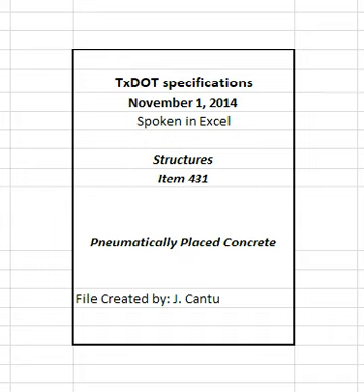Place coats on vertical and overhead surfaces in layers of such thickness to prevent sloughing, sagging, tearing, or debonding. Provide a sufficient interval between successive layers in sloping, vertical, or overhead work to allow initial but not final set.